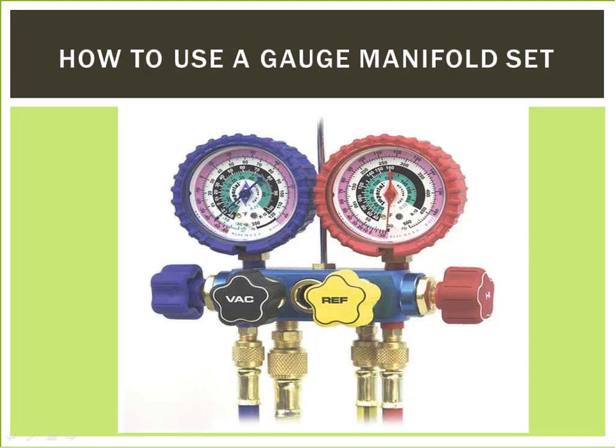Unscrew the red high-pressure hose from the AC unit. Open the red high-pressure valve on the test gauge's manifold and then the blue, transferring the pressure from the high-pressure side of the manifold to the low-pressure side. This will allow the refrigerant to be returned or sucked back into the AC unit. Close the red valve and then the blue. Remove the blue hose from the AC unit. Reinstall the valve caps on the AC unit's test ports.